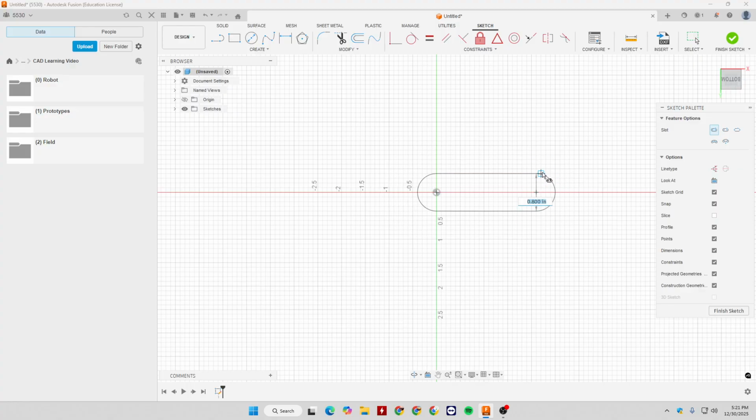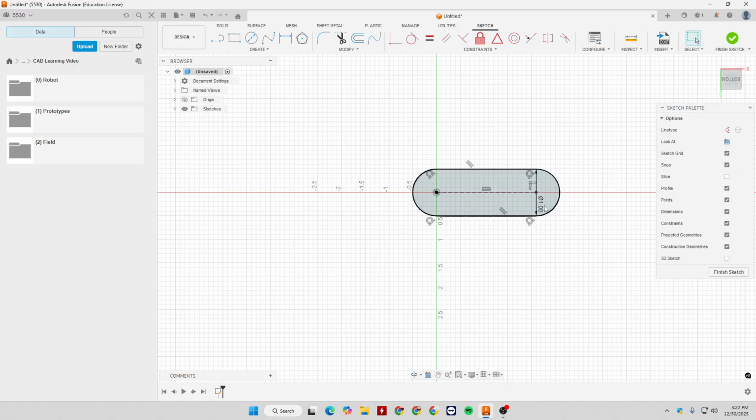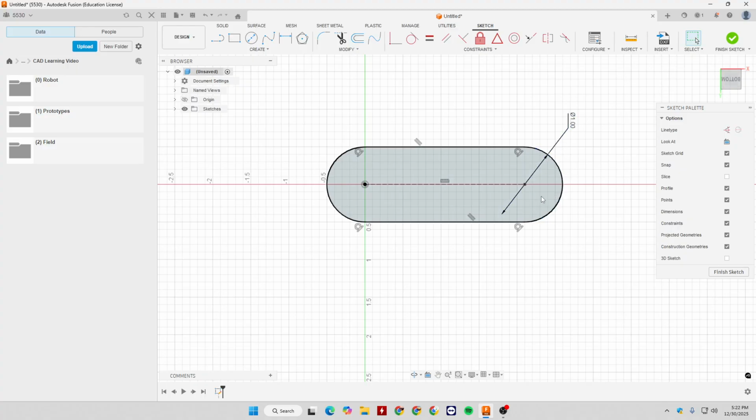So if we're going for a 1 inch, we're going to go for a diameter here actually. So these lines, this circle is well defined. I'm not sure if we create a dimension of this line as 2 inches, the full thing should be constrained, giving us that there. But that is a way to create a slot.